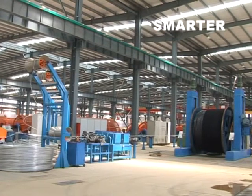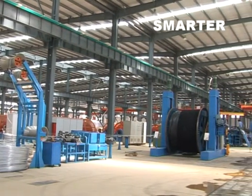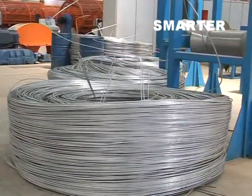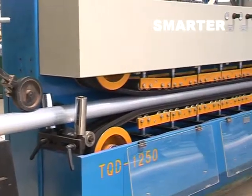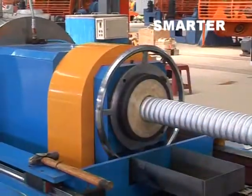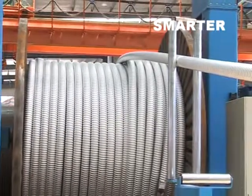Aluminum cladding continuous extrusion line is a new product developed by us in recent 2 years. The machine is mainly used for extruding diameter 9.5 mm aluminum rod to 70 mm to 165 mm tube, which is cladding outside of cable, then rolled to sparring or annular metal corrugating sheets for protection.